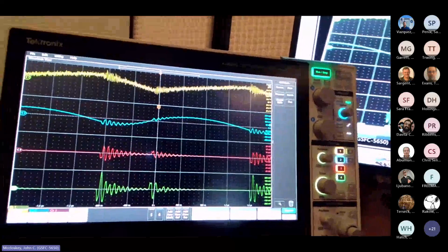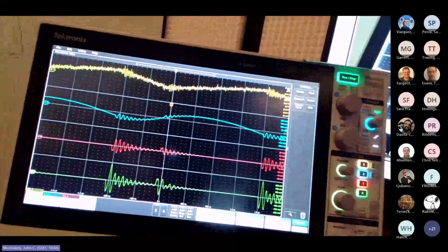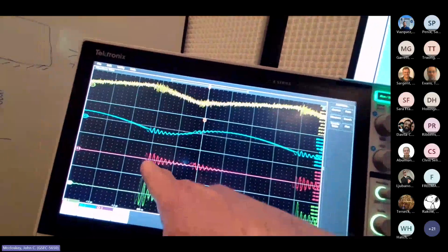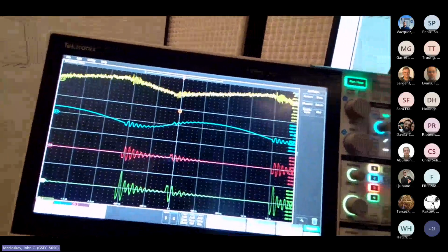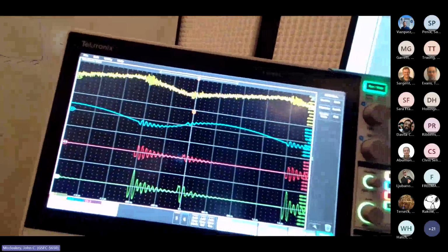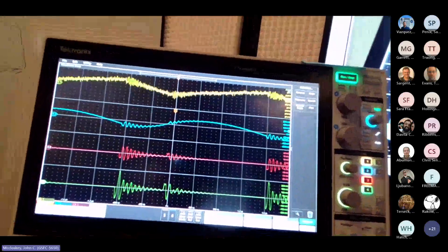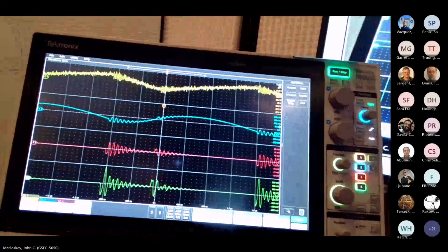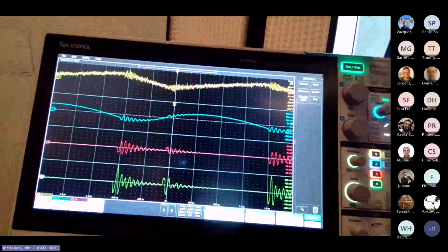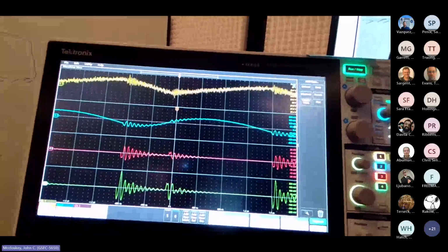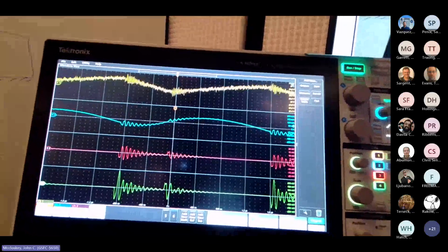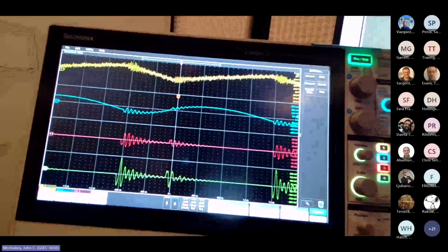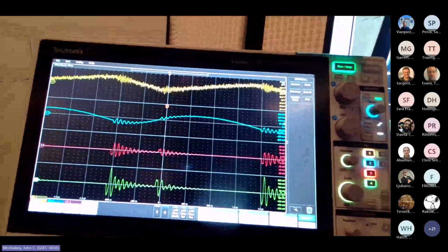So we see that it's comparable, right? But there's a little peak here that's a bit higher with the Fisher probe that the Pearson probe doesn't seem to be picking up quite as well. So if I had to pick one of these probes to use going forward, I'd probably use the Fisher one because that's clearly higher frequency ringing there. There are plenty of cases where lower frequency content is more what we're looking at, and then I'd ditch the Fisher probe and just use the Pearson probe, but there we go. So just another little test and measurement thing to pass along.